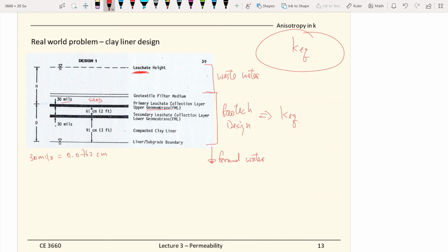So this is 30 mils, and the hydraulic conductivity for this layer is 10 to the negative 11 centimeter per second. This is the hydraulic conductivity for that plastic material. And for the sand layers, I forgot to mention, the hydraulic conductivity will be 10 to the negative 4 centimeter per second. Sandwiching them is again the same sand layer, so this is 10 to the negative 4 again. And then you have another wrap of 10 to the negative 11 centimeter per second geomembrane material, the same thickness.